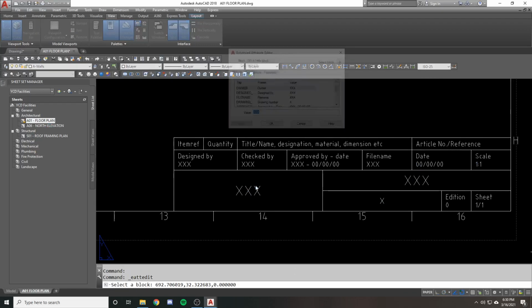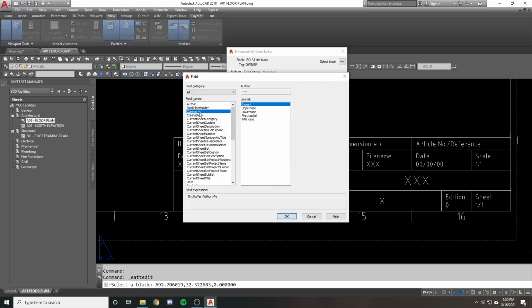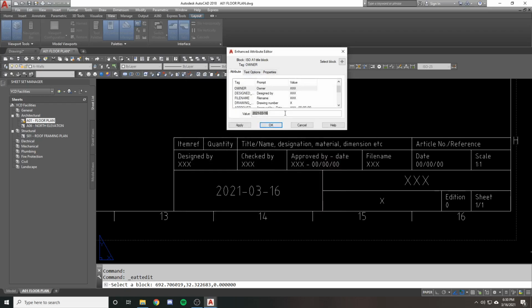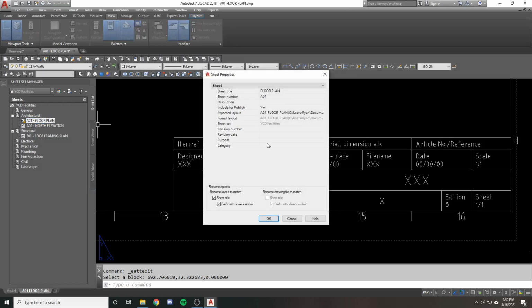So here, where you see attributes and they're just static text fields, instead of that, you'll see something like, I don't know, let's do create date. Notice how it's grayed out. You'll see a field with a value that's already preset. If the value's not in there, it'll say X or dash or something. But if the value exists, it will be grayed out and it'll have the value. In the case of your drawing, your company may have a whole list of custom properties to fill out inside of here.